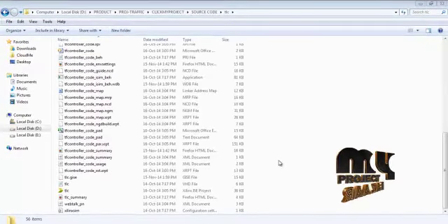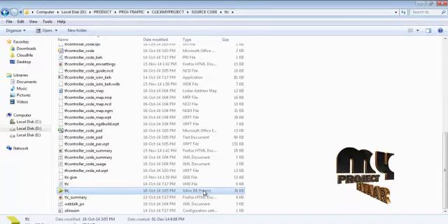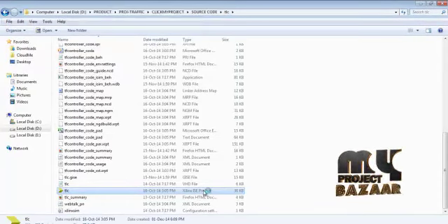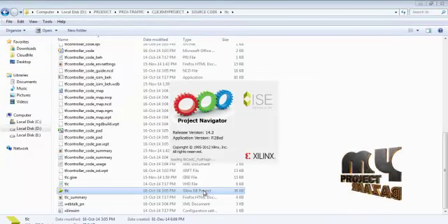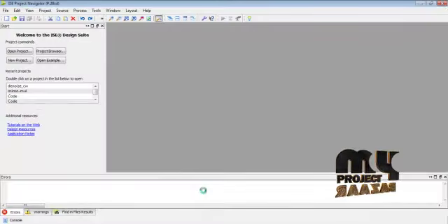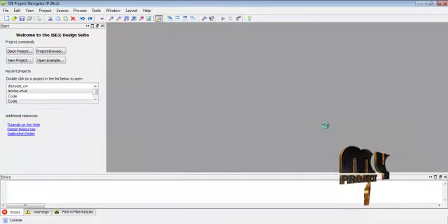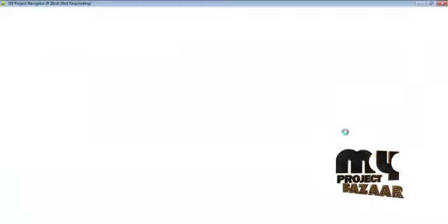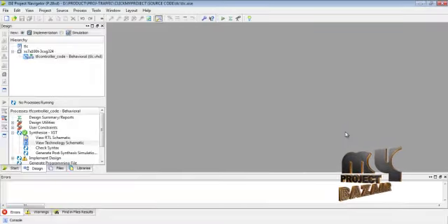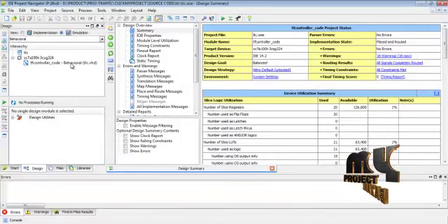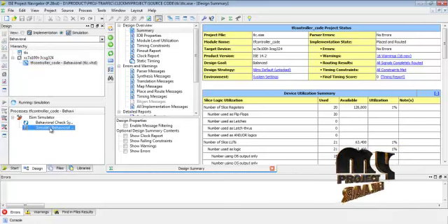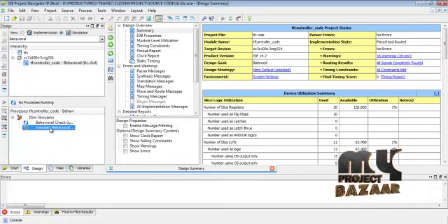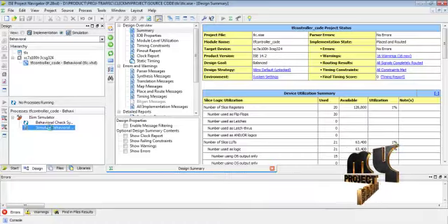And finally we see the output for the product. First we run the traffic light controller ISE project. Our traffic light controller architecture was developed in the VHDL language, using the behavioral modeling process to design our overall architecture. Then we select the simulation, select the traffic light controller code, and run the simulate behavioral model. Then we create the iSim project navigator. This project navigator is mainly used to simulate our process.